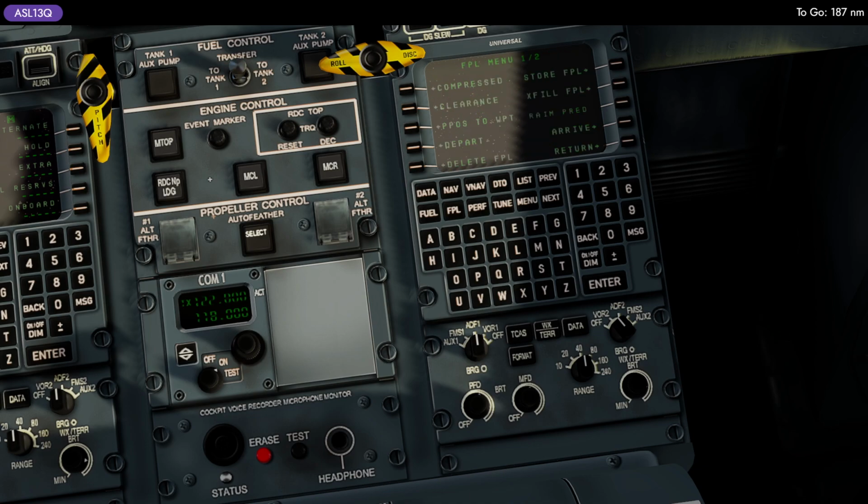So let's go to flight plan, menu, arrival. Arrival is going to be 12. We are going to use RIGMU 2 Kilo, which is number 16. Yes, that is the runway 12. We are going to use the ILS approach, that is number 2. And we are going to use the DEVDA transition, which is basically straight ahead. That's it. So now let's just double check there are no discontinuities.